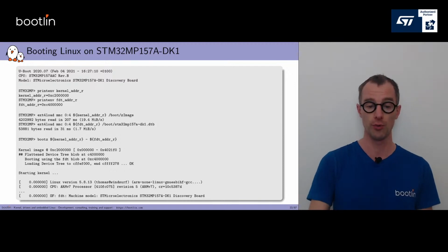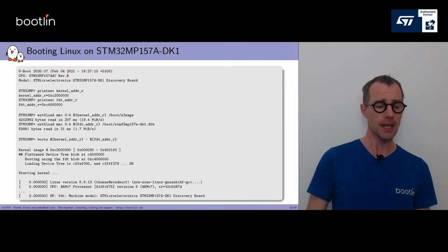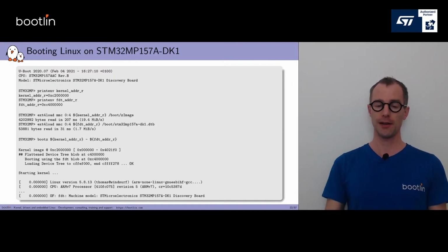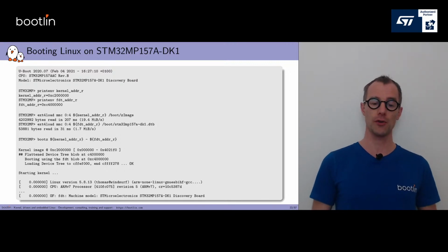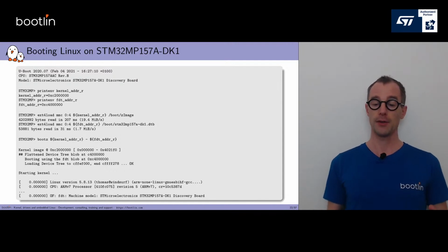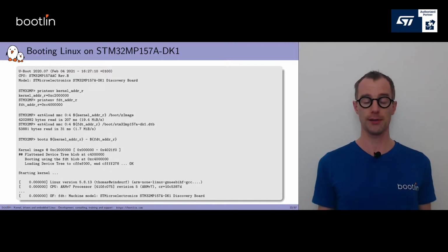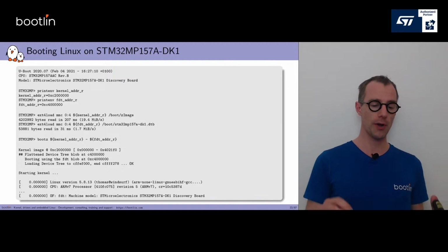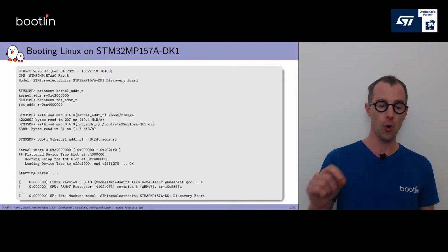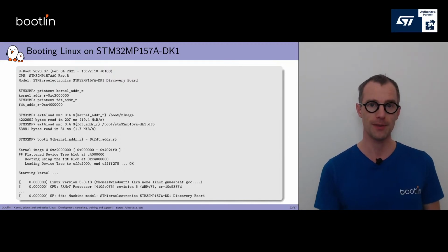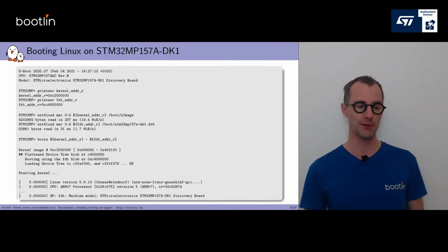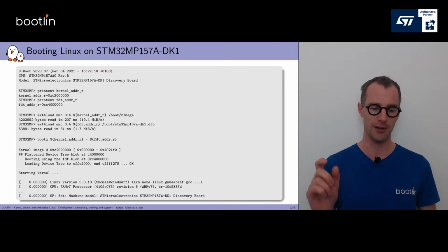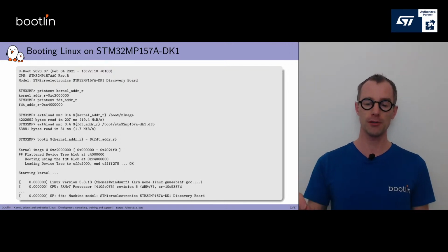It is going to boot with that device tree blob. And then it starts up the kernel. The kernel announces that this is Linux version 5.8.13, and it's telling us which ARM core we're running on. But also very shortly after the boot, it tells us OF, Open Firmware, FDT, flattened device tree, that's why I insist on the terminology and acronyms, and then Machine model, and it gives us a long string describing the platform.